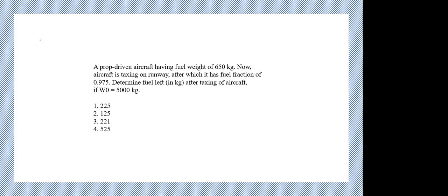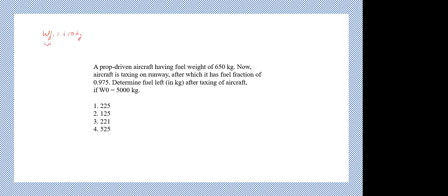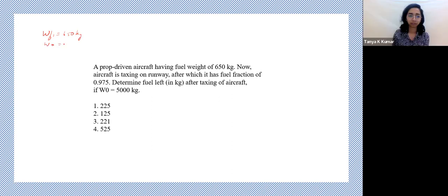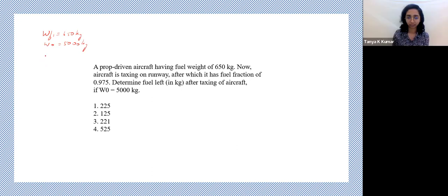Ma'am, W0 is the total takeoff weight, na? Yes, including the fuel. Exactly, yes. So your initial fuel WF1 was 650 kgs. Answer is second option, 125. Can you tell me the steps that you followed? Just multiply the weight fraction by the total weight and subtract. Exactly.